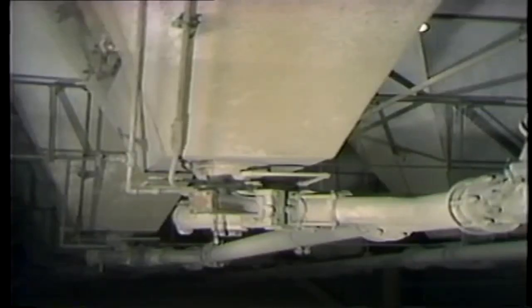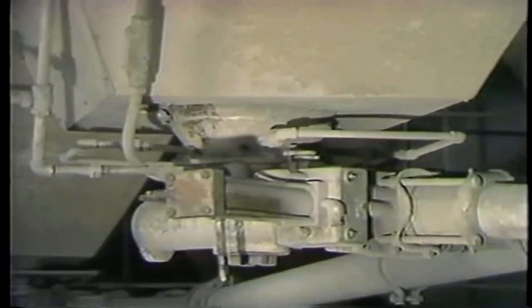The wet fly ash will insulate the boiler tubes and prevent efficient heat transfer, or it may clog the air preheater. Wet fly ash will also stick inside ash hoppers in the fly ash handling system. If the problem is severe enough, the boiler will have to be shut down and the ash hoppers opened up and cleaned. While the problems we've just mentioned can affect the operation of a boiler, in most cases a tube leak does not require an immediate shutdown.